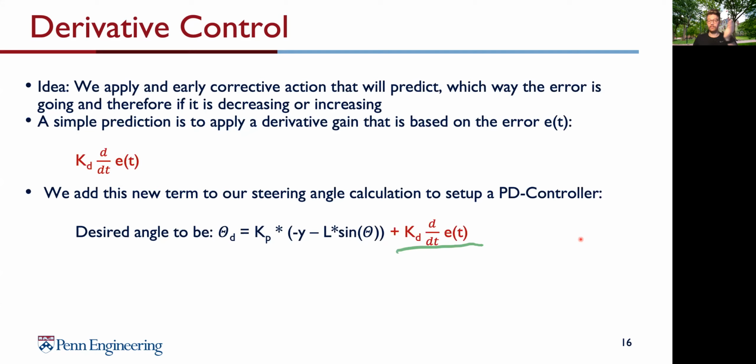In addition, the trajectory correction takes longer because it needs time to smooth out, which means that unlike in a proportional controller, where we might just drive straight to the center line but overshoot afterwards, now it takes a little bit longer, and we are approaching the curve more slowly.